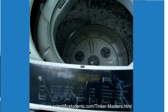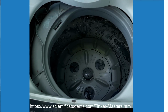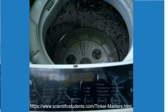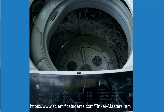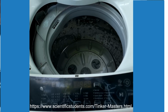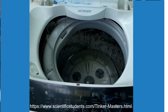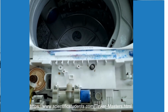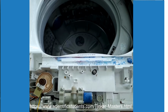So we have tested one by one. So what could be the problem? We have seen the main drum and the motors and everything. Every time I switch it on, exactly at half the process, it stops and gives me an error 0E. I figured it out through the user manual, and finally I came to know the 0E is for drain out issues. But the drain out in the beginning of the process is working nicely, draining whatever water is there in the drum. But why is that problem coming in between?